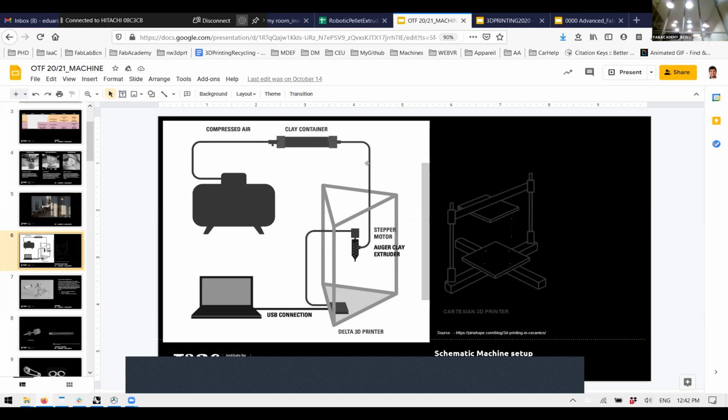So you're printing this super nicely, and suddenly a bubble of air, which is really common, happens and basically blows up your print, destroying it. So this system is really nice for making material tests, or if you mix the material really well. If you mix the material really well, you will not have any problem, but you need to be careful. By the second or third time, you will start knowing how to mix the material properly to avoid the bubble.